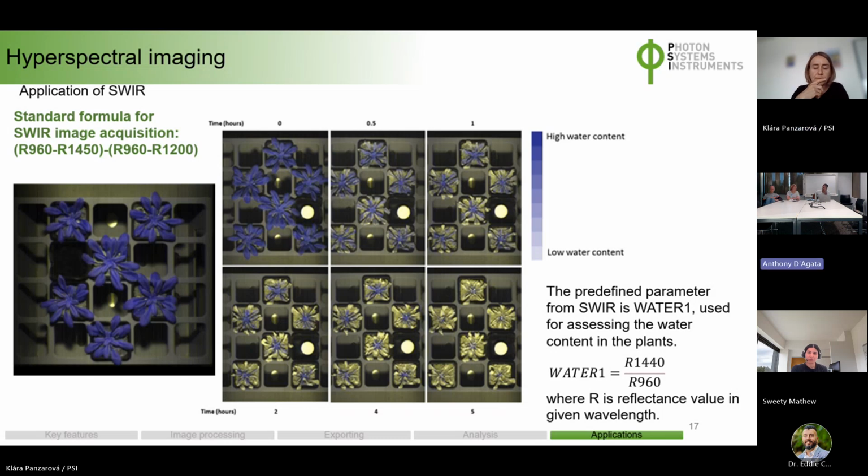Okay, so the RGB does the panning, so you get the same pixel size. Exactly, because our RGB camera is very different to our VNIR. So those are the two options, because we have a few installations where we have solely short wavelength infrared, and then it's managed this way, because there are really cases when it's getting difficult to do robust image segmentation only with the short wavelength infrared.